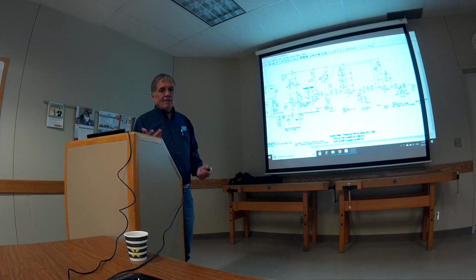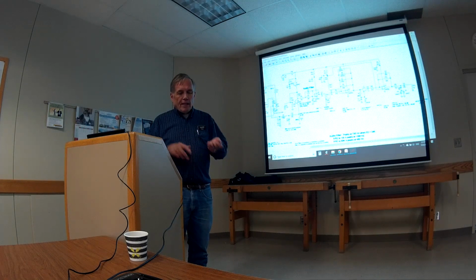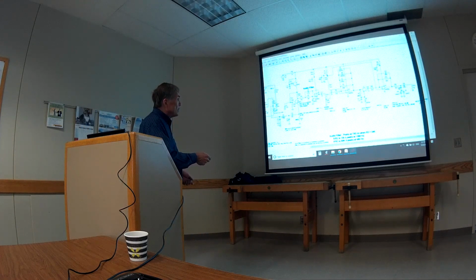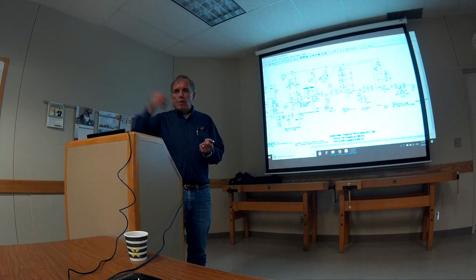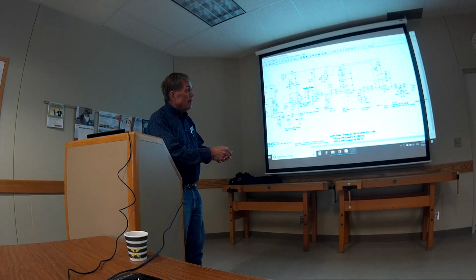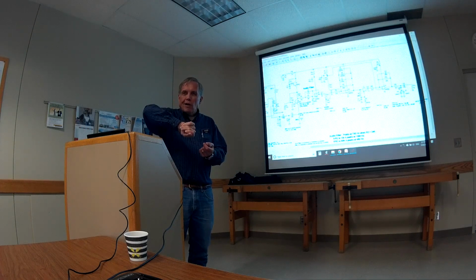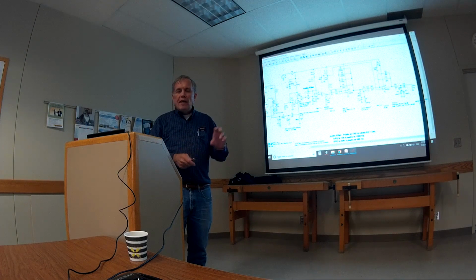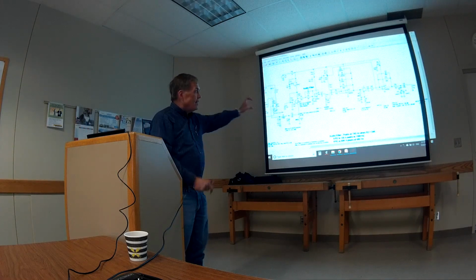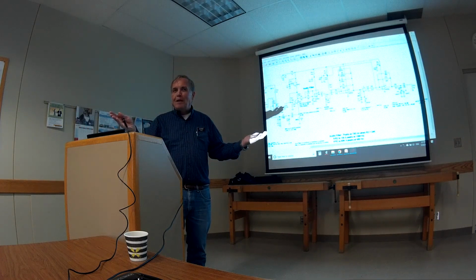Now, to actually inject the signal, I have a little simple audio oscillator with an attenuator on it. So I stick the audio signal right up here, for example, at the volume control, okay? And I look at my oscilloscope to see how much signal I'm putting in. Then I put the scope right here on the speaker lead, and obviously it's much bigger. Then I put the attenuator on, 10 dB at a time, until the signal that I'm looking at is exactly the same as what I had put in before. Then whatever my attenuator says, that's how much amplification I'm getting.